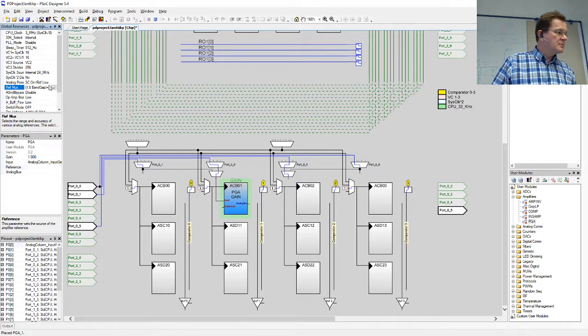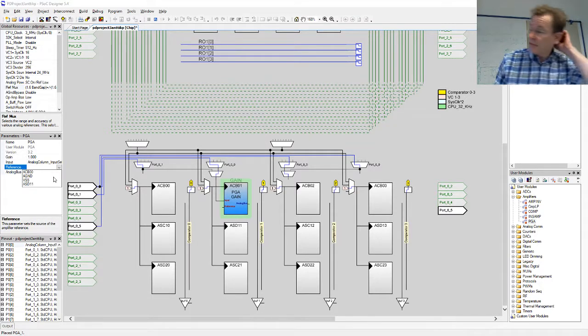Back to the business. So I have the 1.6 times band gap reference marked there. Good. And then on the first programmable gain amplifier, I could also use the zero reference, since the operating volt is 0, because I already know that my sensor is referenced to 0.